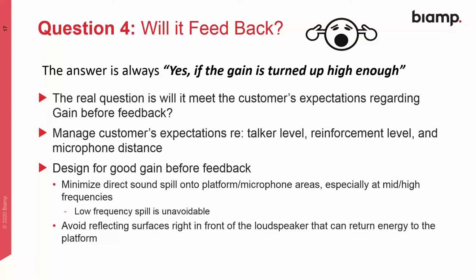I had another situation where a loudspeaker was aimed overhead center at the audience, but right in front of the loudspeaker was a lighting well, and this reflected sound back down into the microphones. I ended up putting flame-proof sound absorbing material in the light well, and they got much better gain before feedback because we weren't reflecting the speaker right back to the microphone.